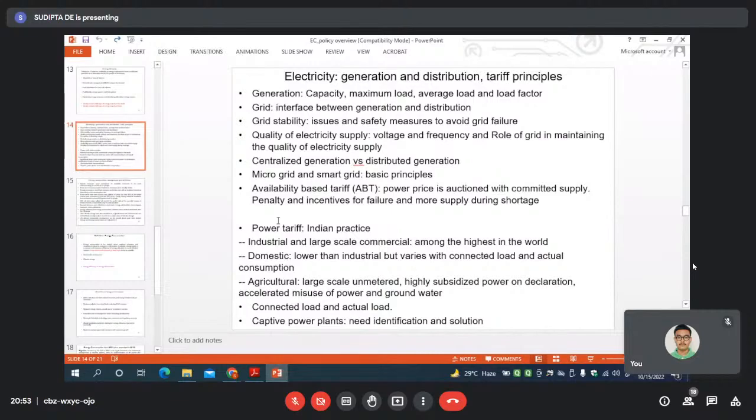But your actual energy consumption, because load is a rate, is per unit time, not per unit electricity. That being at peak doesn't always mean the total energy consumption on that particular day is high. One particular peak may be very high, but maybe over the day you have consumed less power, so the overall energy consumption is less. Billing will not be on the basis of the peak of that particular demand, but on the basis of the overall energy consumption. But interestingly, your actual demand cannot exceed your already declared connected load.